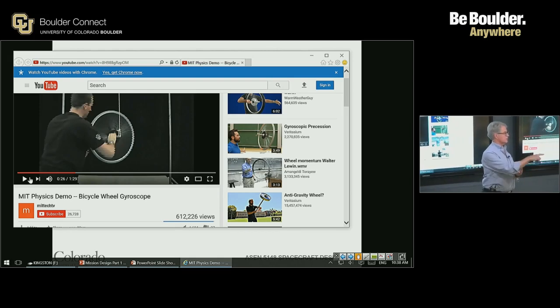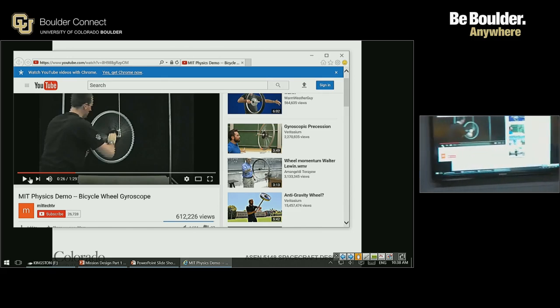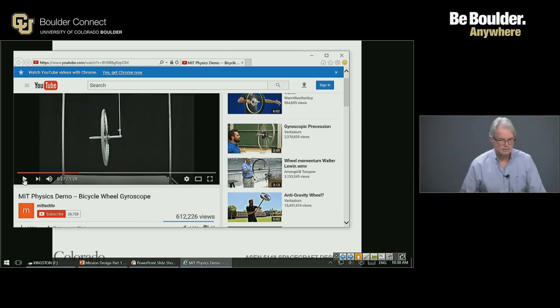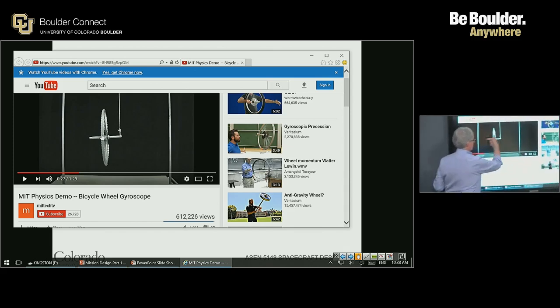It's got energy. It's in a state. It has angular momentum. And it's trying to resist gravity because gravity is trying to torque it, right? Yeah. Okay. So let's look at what gravity's doing when he lets it go. What's gravity doing? Trying to torque it, right? It's creating a net torque. Angular momentum vector is sticking out that way. What's the gravitational torque doing? No, it's creating a moment. Right-hand rule, yeah, it's putting a little delta H sticking out of the board, right?